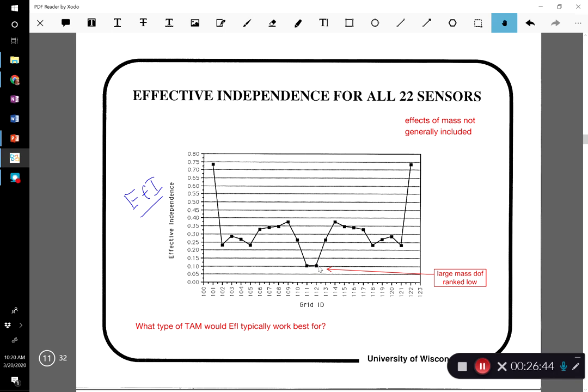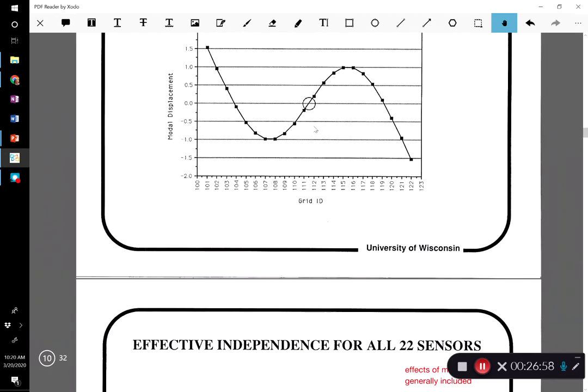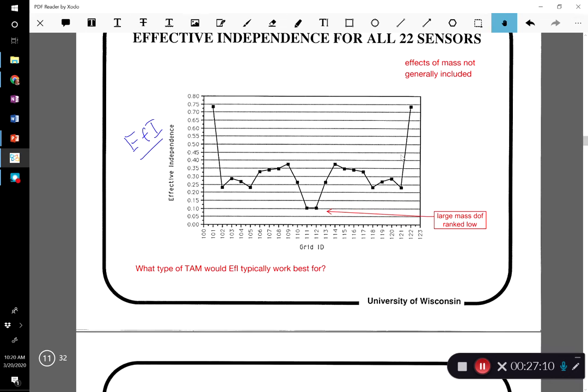And you can then proceed to place sensors. So what you would do is you would throw out these two, since they're the least important. And it's interesting, those are the two points where the concentrated mass is, the core of the satellite is. It's thrown those out as it's considered both the signal strength and the motion and the independence of each point.